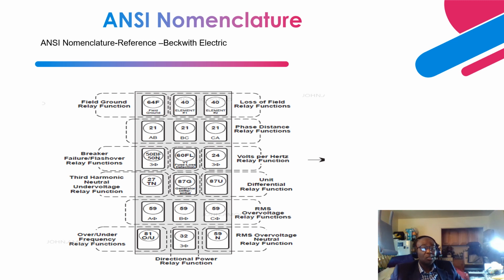As you can see over here, this is also based on impedance. It's an impedance-based relay, so it utilizes CTs and VTs, voltage elements, to calculate the impedance. It is also made in such a way that it is directional, basically pointing towards the generator as well.